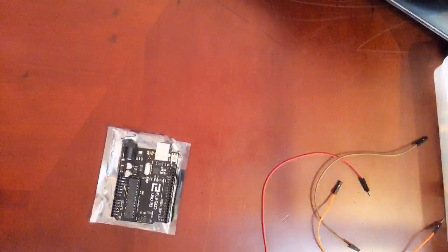A whole bunch of more data there. Pin description. The VDD power supply is 3 volts to 5.5 volts. The data serial signal is a single bus. The ground is the negative power. So let's see where they want us to connect.